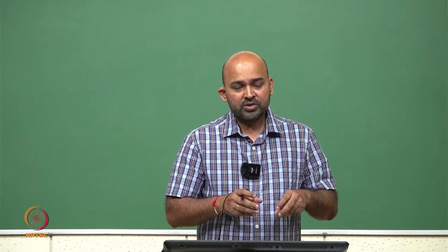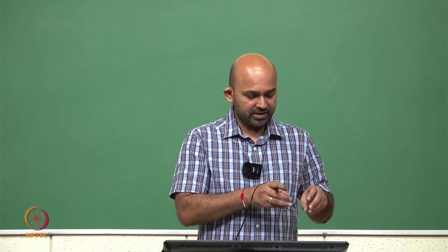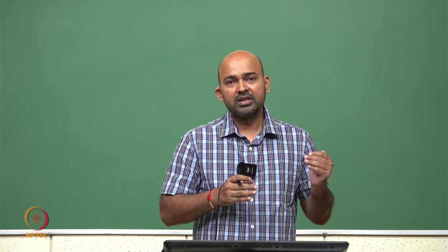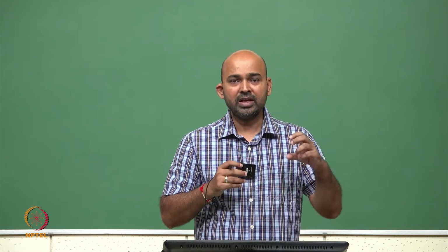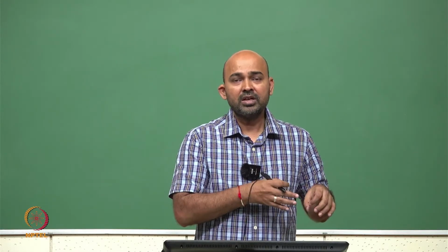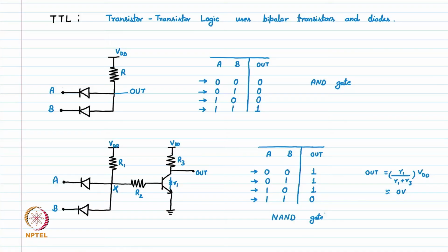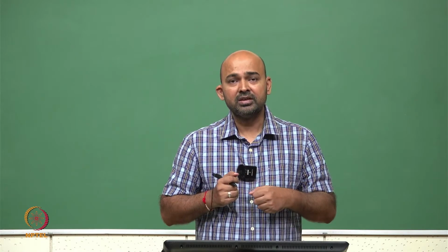The first issue is that we have to have certain amount of protection at the input stage A and B. If the input is, let us say, overshooting or undershooting, at that time we should have certain protection which can protect these diodes from that high voltage stress. And at intermediate nodes, where the junctions will immediately turn on or turn off, we need to protect the intermediate circuitry from the reverse currents which are possible in this kind of circuit.